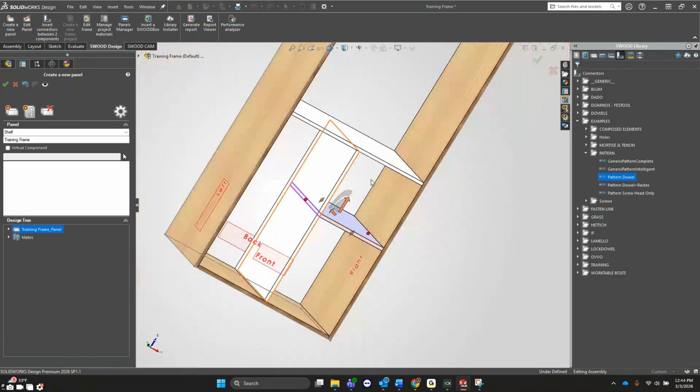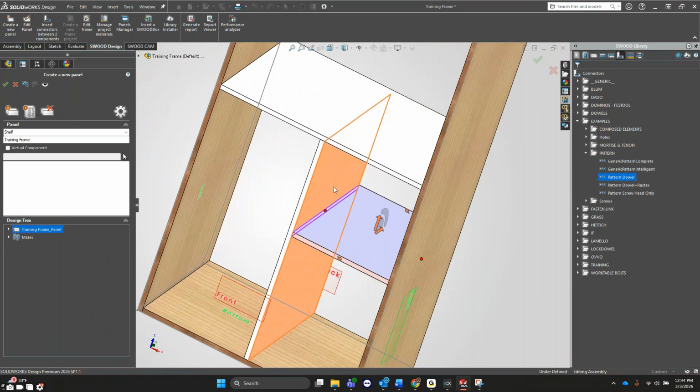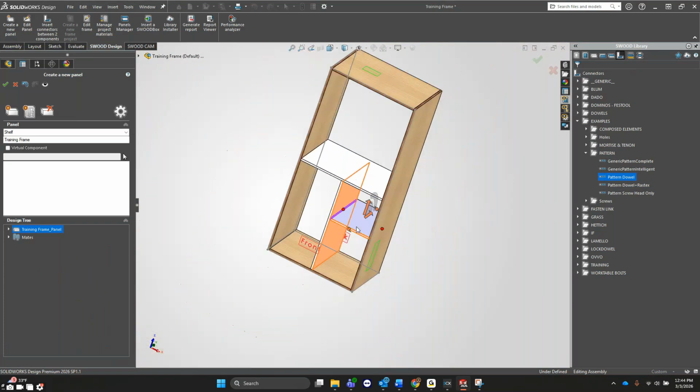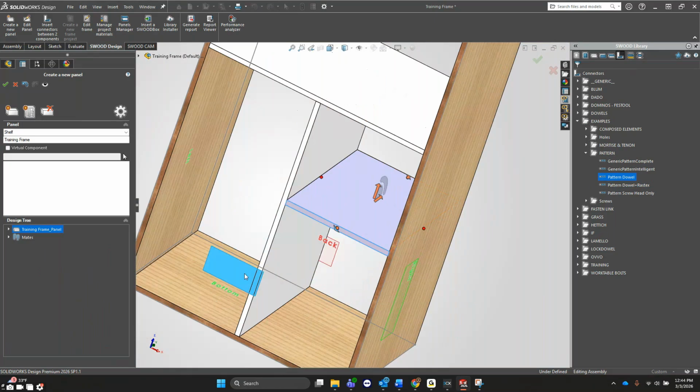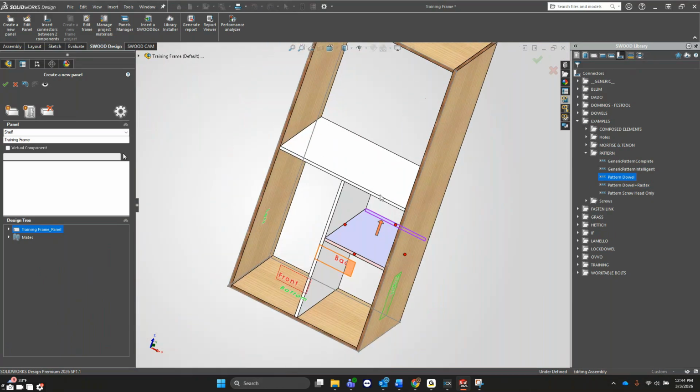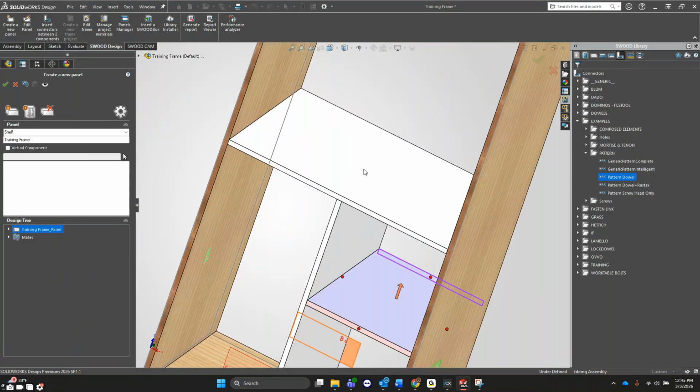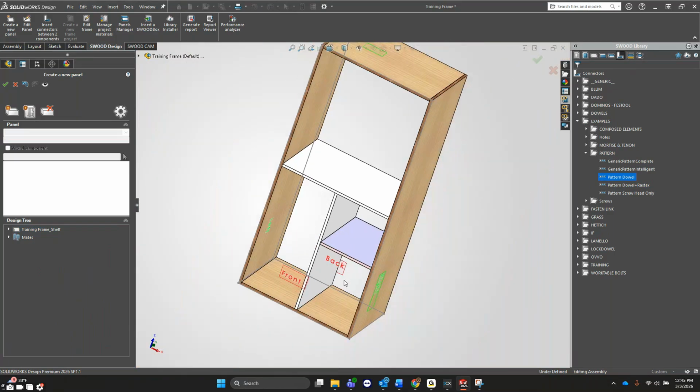So there's another thing that we could do here, and we'll get into that when we do more frames examples as well. But we could also set this up, like we could have set up a plane here that's equidistant between the top and the bottom, and then it would just be a matter of snapping the panel to that plane. So that's another way we could do it. I'm not sure if you guys have done the reference geometry planes thing yet. Have we done that at all?